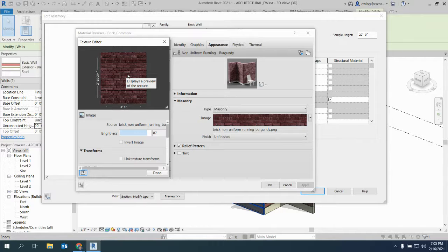But if we go to the appearance tab, right, and we click on the image, here's where we can map out the actual brick or whatever that's going to be, right? If you got on the presentation we all did for our professional electives, you probably saw me going through Slocum Hall. And I just went up to the columns, went into the marble room, just took pictures of that material. And that's how I mapped it out onto the actual building to get that realistic look. So I went way deep into some dialogues, Anya, just to explain to you how much is actually behind the scenes in Revit. It doesn't look like a lot on the surface, but it's a pretty powerful program.